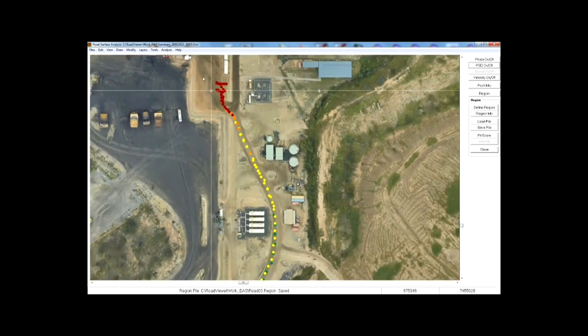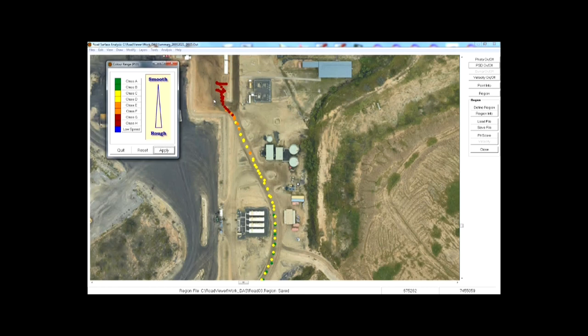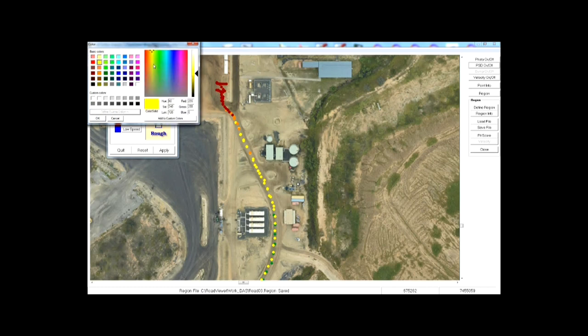The colour coding of the power spectral density menu can be shown by selecting colours. The colouring is according to an ISO standard where they define roads according to Class A through to Class H, and they are colour coded appropriately. Class H is a very rough road, Class A is a very smooth road. If you wish to change the entries, you can, for example, click on Class C and give it a different colour. We'll do something extreme, perhaps a light blue.